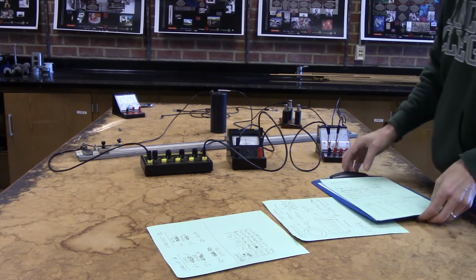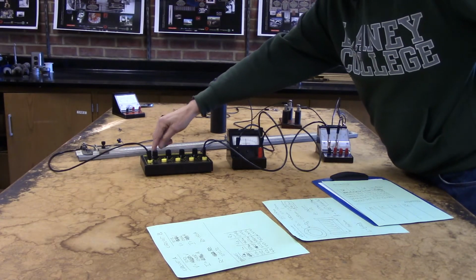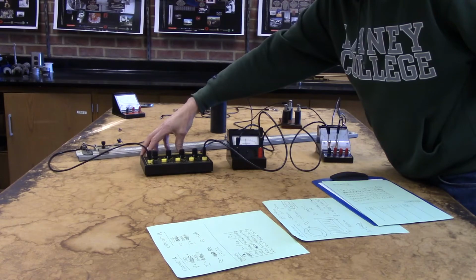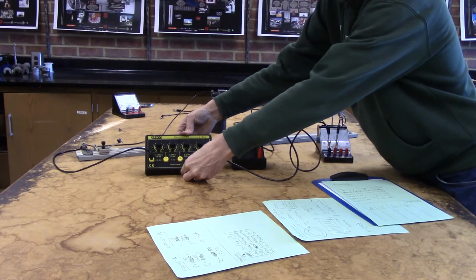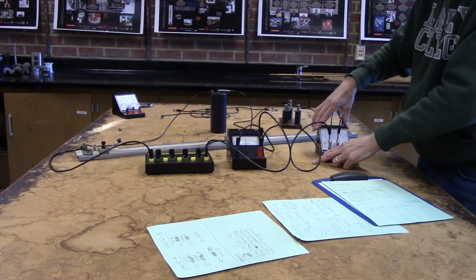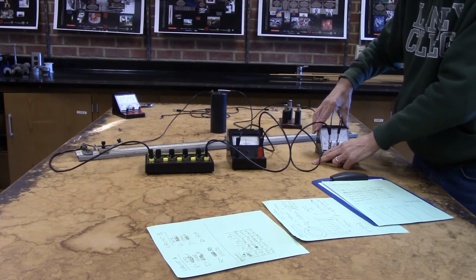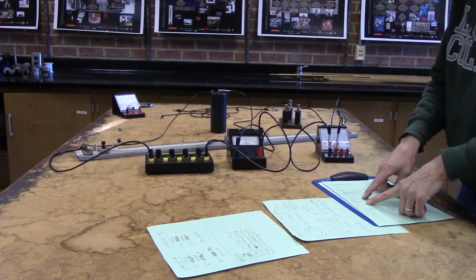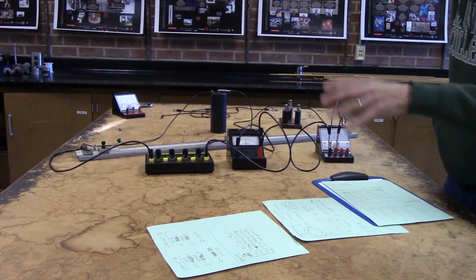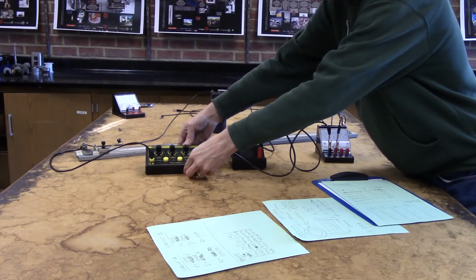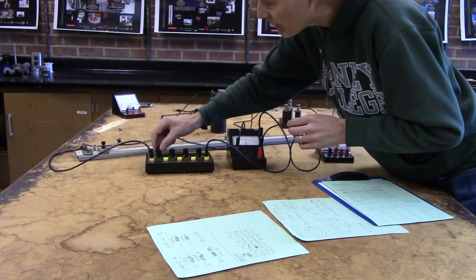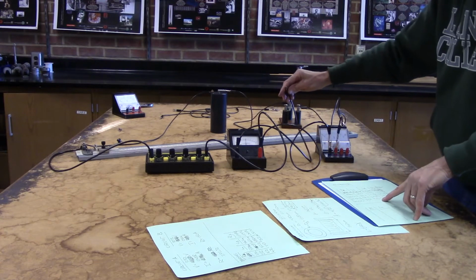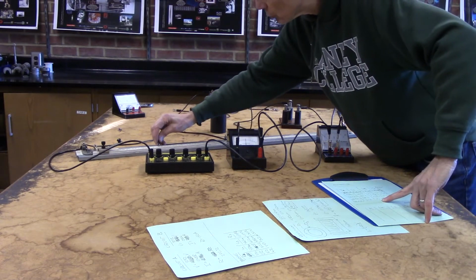So I went through and I started out by setting the resistor box at thousands of ohms, because I'm expecting, even at this low setting, the voltmeter will have a lot of resistance. So I did start out with 1,000, 2,000, 3,000, 4,000. I did some measurements at each of those settings for the resistor box. And the same thing as before. So right now I've got it set at 1,000.